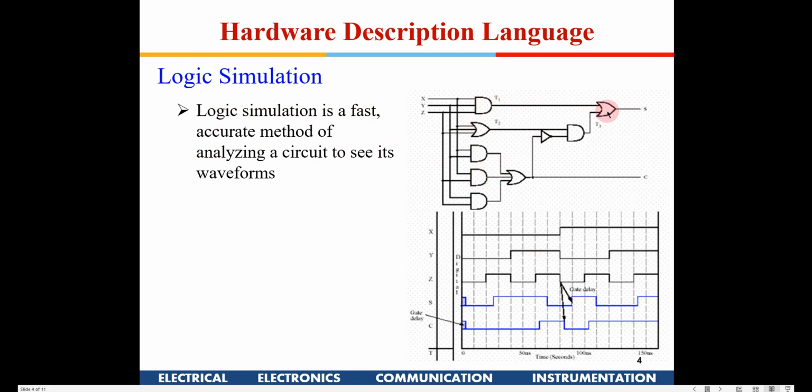If I run that code, this circuit will be implemented based on the code which I write, whatever the functionality. In this particular case, it is a full adder, with A, B, C, sum and carry. So I write a program for a full adder, and this circuit will be implemented on its own.